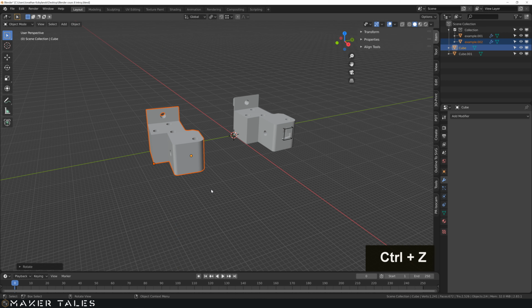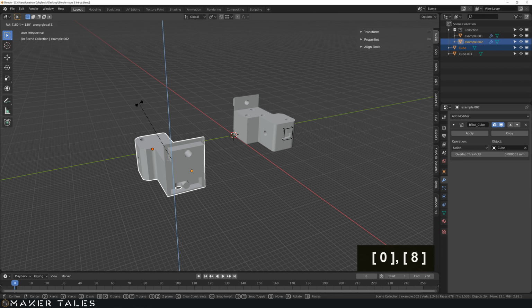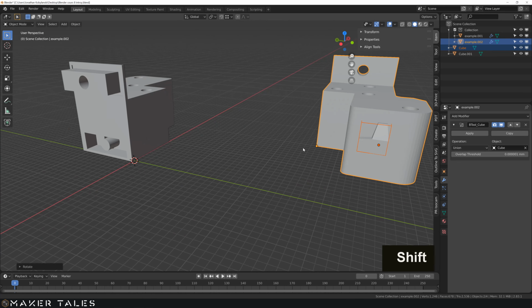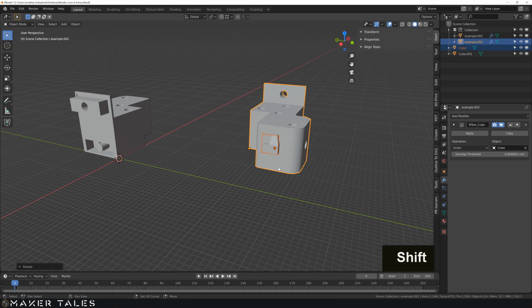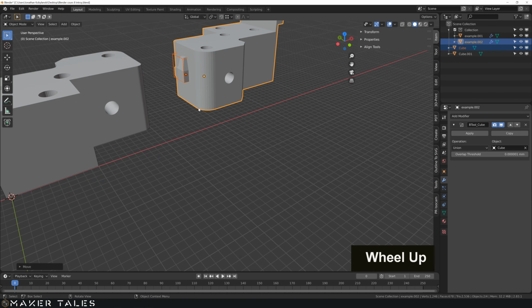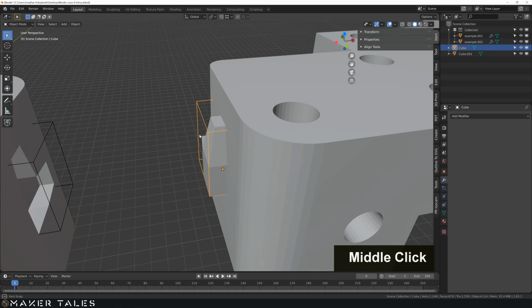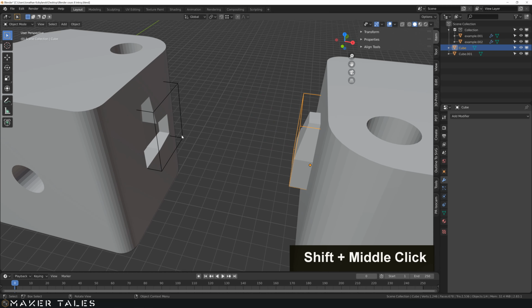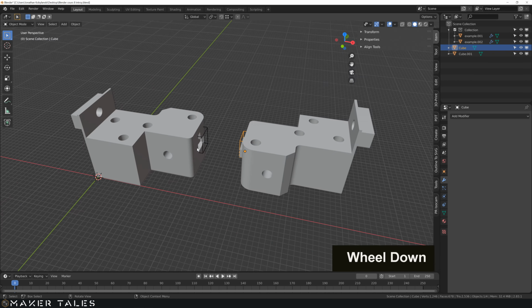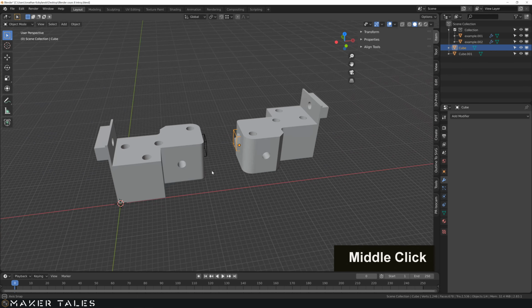Oops, I've got to not have that set to individual. I've got to have that at median point. Select those. Let's go ahead and rotate this. Let's go 180. Now let's go ahead and use, actually let's not use anything too complicated. Let's just move this around over there. So then you can see how these here would join up. That we now have our lovely little holes individually to our connecting faces using linked objects and the booleans that we learned in our last video.